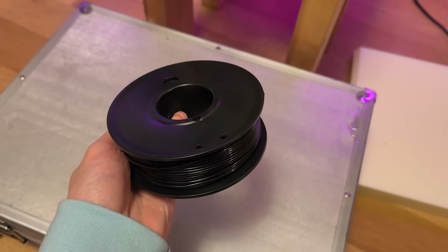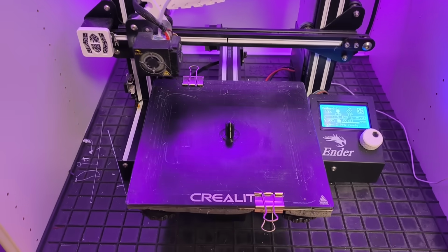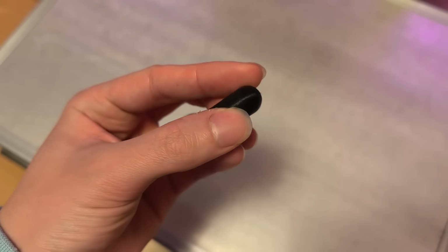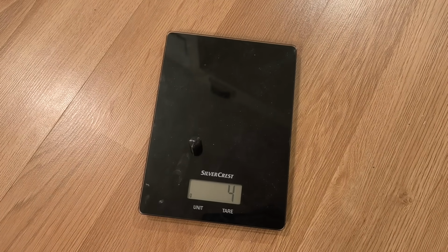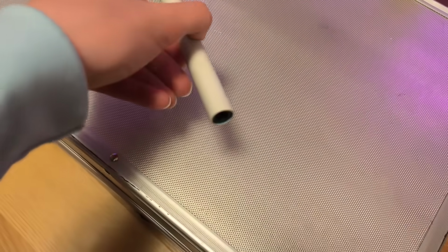For the projectiles that this cannon is going to launch, I designed this cylinder with a rounded end and a hole in the bottom, which I'll print out of TPU filament, because it won't shatter and impact in the same way as hard plastics like PLA or PETG would. This is important because I'll be testing it indoors. It has a mass of 4 grams and it fits into the barrel with minimal friction and a minimal gap, and will not have that much leakage.